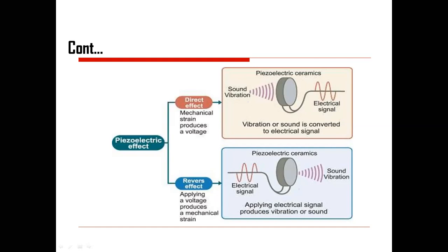The best example is heart sound measuring. In heart sound measuring, you place a piezoelectric capacitive type of sensor on the chest, and the pumping action of the heart increases or reduces the vibration and generates an output in terms of an electrical signal. The back and forth motion of the heart during pumping, contraction and relaxation, will increase or decrease the displacement gap to the sensor, which generates an electrical output. By this means, you can easily measure the variation in the displacement.